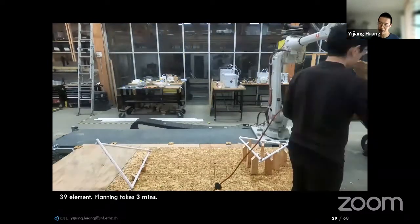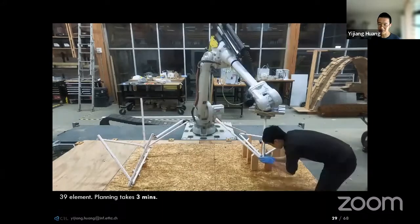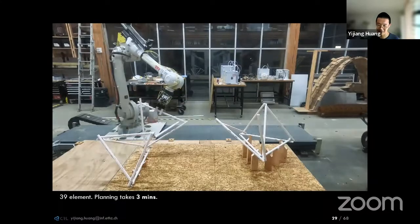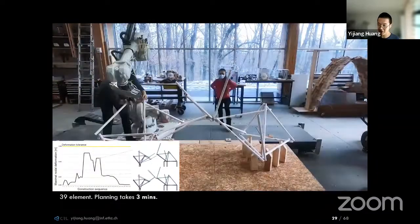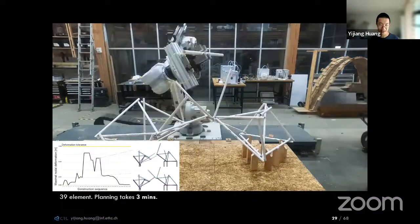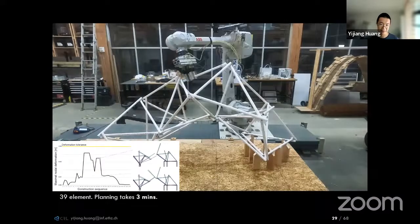In contrast to a naive forward search algorithm that cannot terminate in hours, our approach can find a feasible plan for this fairly complex bar structure in 3 minutes and outputs a detailed sequence and trajectory that can be directly loaded on the robot. And we can also plot the maximum nodal deformation along the assembly steps, where each dot on this plot represents a partial structure simulated with the FEA along the sequence, and the y-axis is the maximum nodal deformation of that step. And we can see that the deformation is really controlled below the prescribed tolerance, indicated by the yellow line.